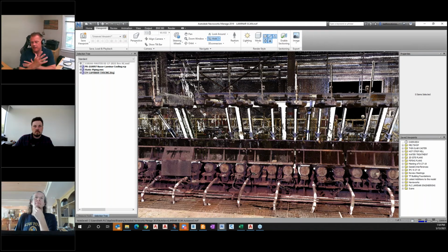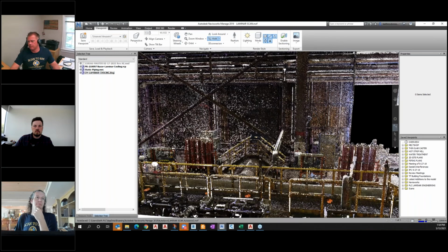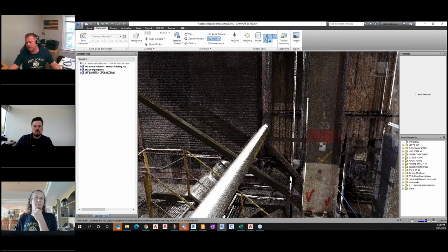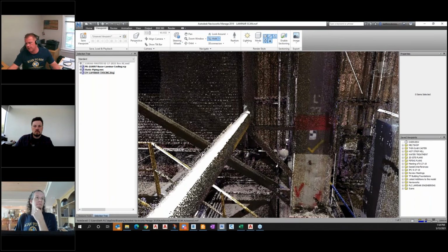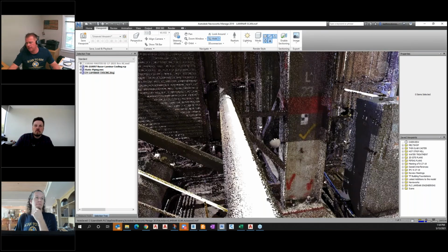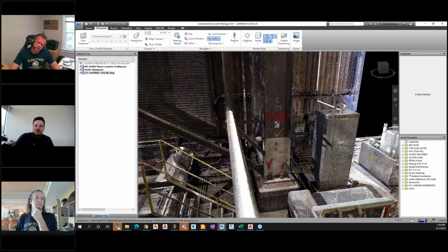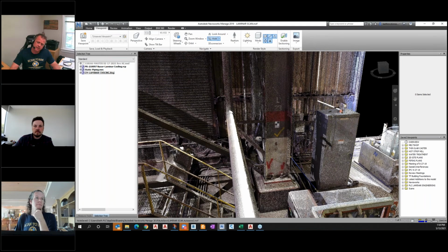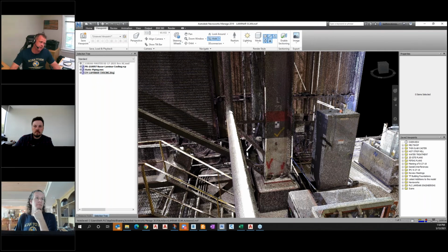And then once we get into the shutdown, we're ready to put the new machine in because everything's already laid out. We'll be using this, there's all of our datum there. We've got survey targets. We got spheres. We actually have a specific type of prism that measures the same distance from the end to the center as these spheres, real fast to set up and resect in off the total station.